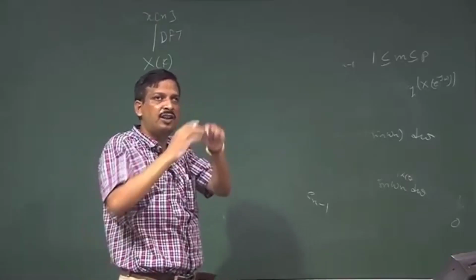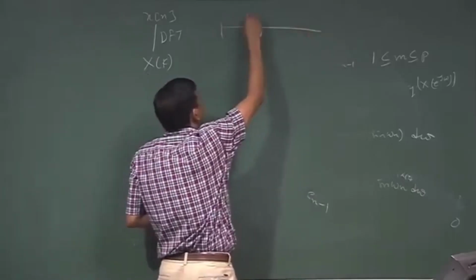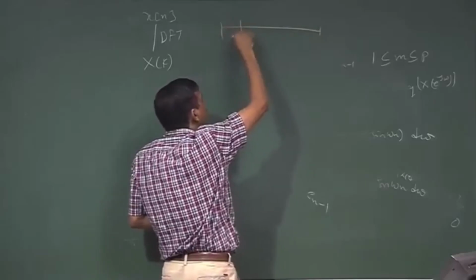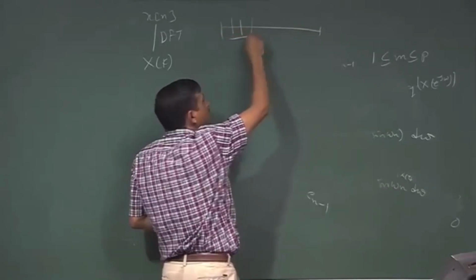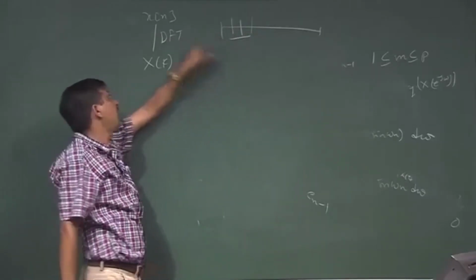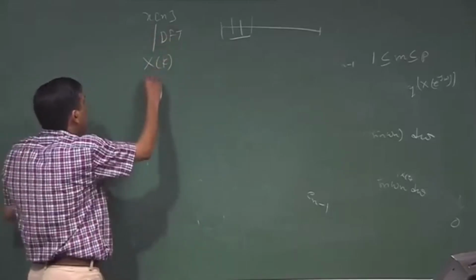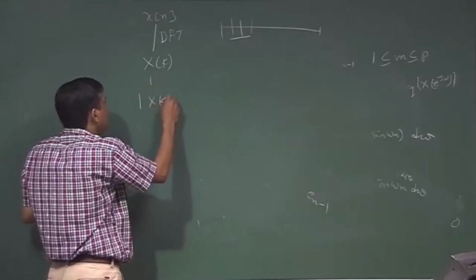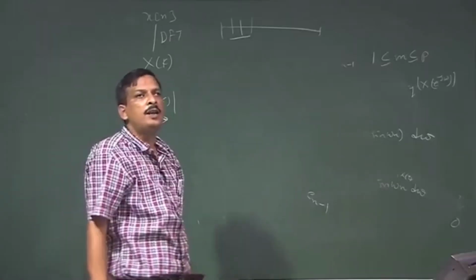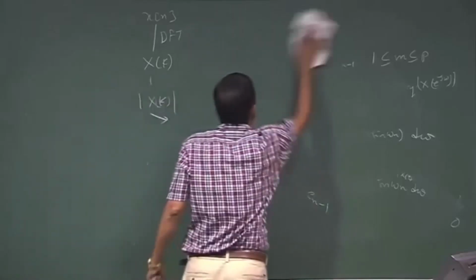Instead of taking the whole signal at a time, I pre-emphasize the whole signal, then cut the signal in a frame, in a window, then shift the window by a frame. So, after framing and windowing, if I take the DFT, I will get xk. Now, if I calculate mod of xk and plot it with the frequency, then I get the spectrum of signal xn.